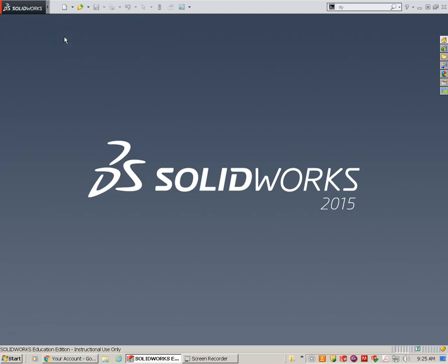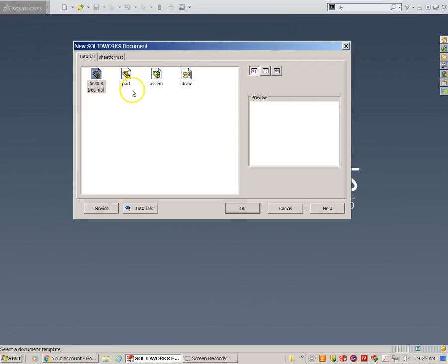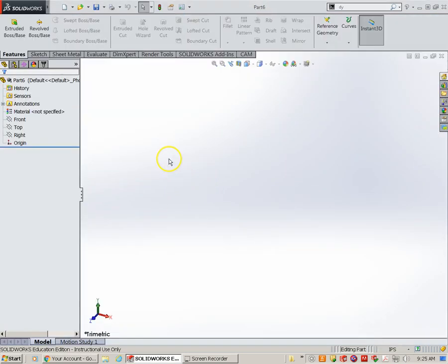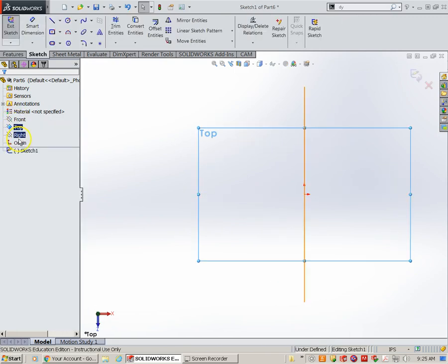Okay, we're on Chapter 6, page 6-11, SolidWorks Basic Tools. We're going to draw the styrofoam box. I'm going to go to New, New Part. Notice I have my ANSI standards set to 3 decimal places. Units are in inches. So we're going to start on the top plane this time. Create a sketch.